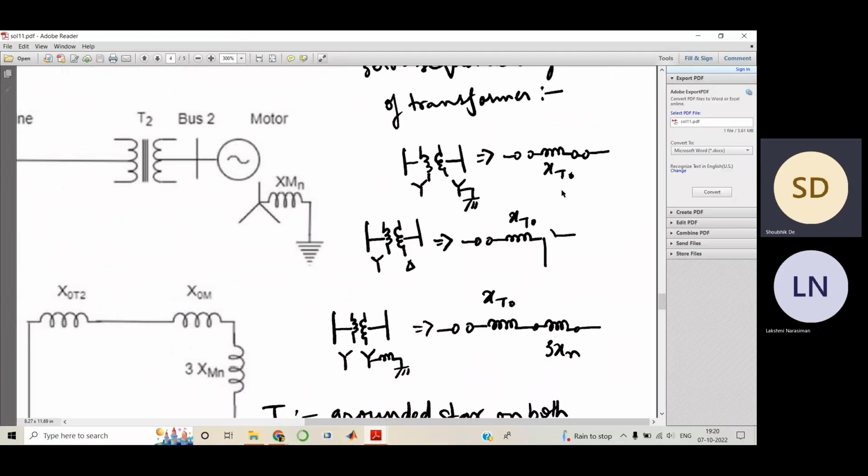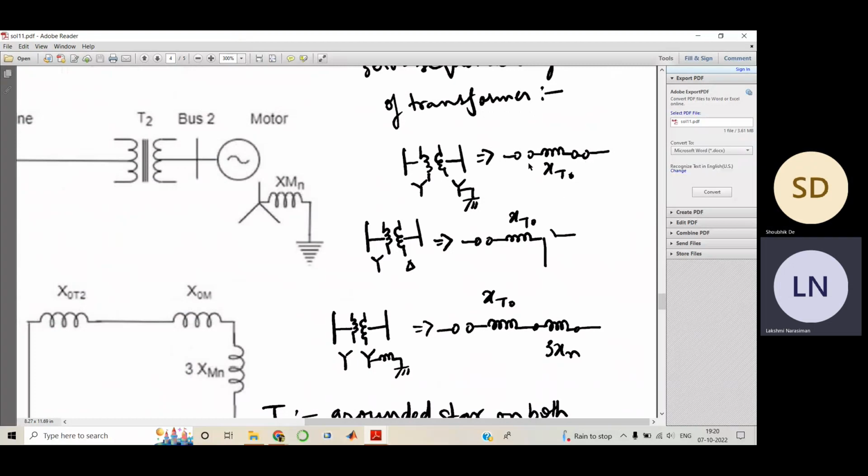Okay. You can't represent that, right? I'll tell another way. On the right side, the two dots are there, right? You have connected that one. Open this one, and the left side is open, right? Just make it short. How will that make a difference? Both are the same, right? Or should I not represent it in that way? Why am I representing in this way instead of that way? Because what I'm understanding, both are going to be the same thing. I'm not going to have the zero sequence flow anyway, the circuit is open. I'm not going to have the flow at all. So what is the difference?